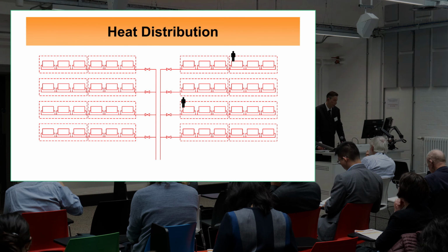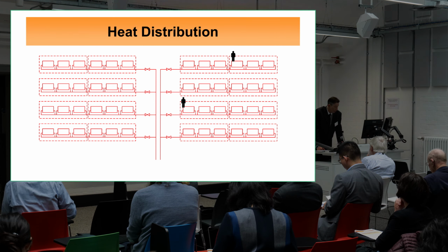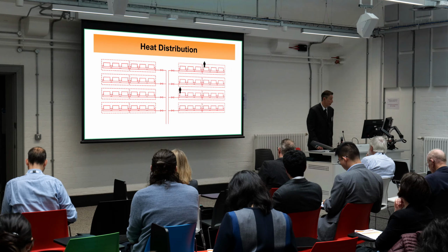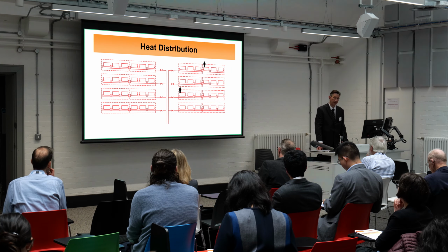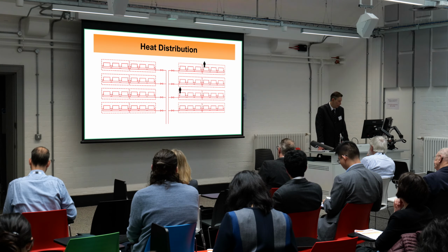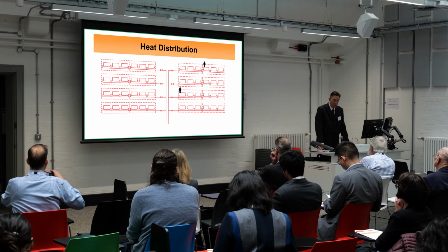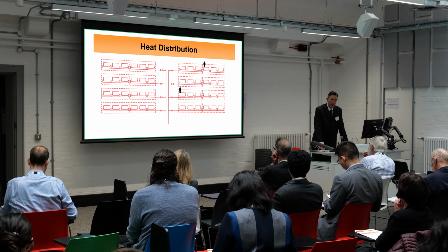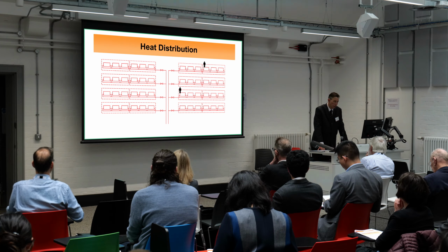So with a large building, we can have to heat up 10 or 20,000 litres of water from ambient up to 60 degrees, say, at startup, in order to distribute water to every radiator. And this type of control is effectively contingency-based control. We're generating heat on a contingency that somewhere a radiator may need to use it. And obviously, that is not a very efficient way to heat a building, particularly these days with greater diversity of occupancy, greater levels of unoccupancy.